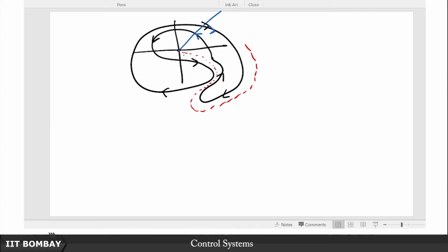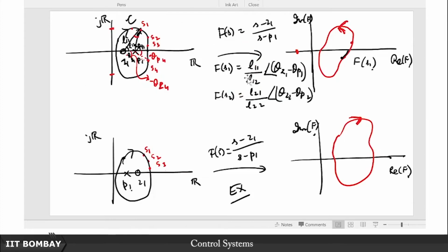So it turns out that you don't always need to look for an opening or a path like this to escape and then understand that there is no encirclement. In the case of one pole and one zero it was very easy, because it's obvious to see, with the kind of contour I chose here, that this point is not encircled. We understand this encirclement notion intuitively.